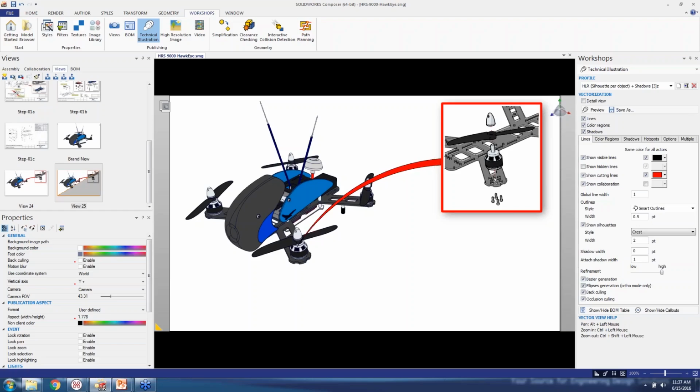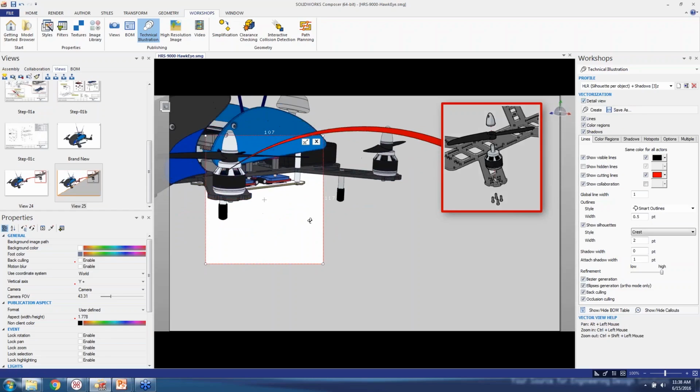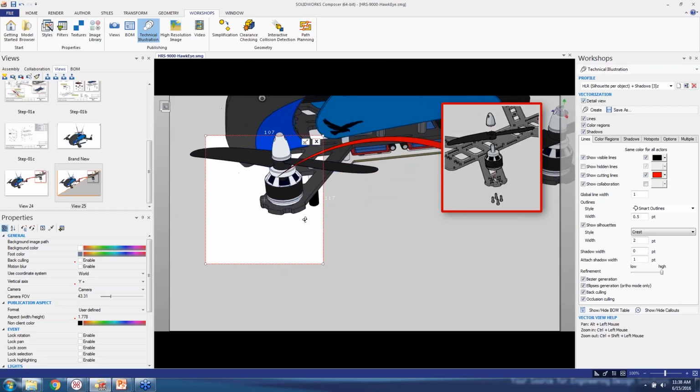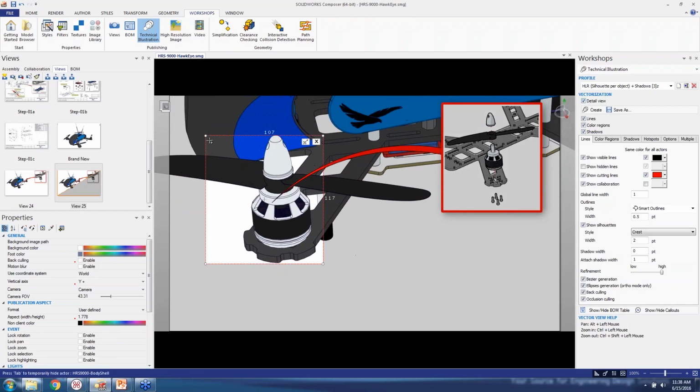Once you have the steps down like this, the rest is just using it over and over, getting used to the tool, and evolving it. Again, this is a new process, so it's going to get better and better as we go through and find these little tricks. But one thing I found that works really good once you get to this stage is we want to do another detailed view. Let's go ahead and say detailed view, and I'm going to rotate and move this guy just so I can see that motor with the fan and everything.